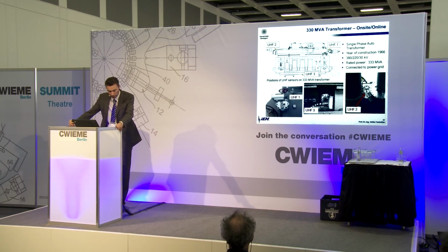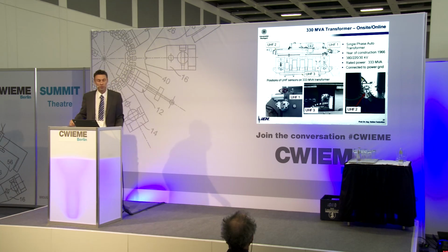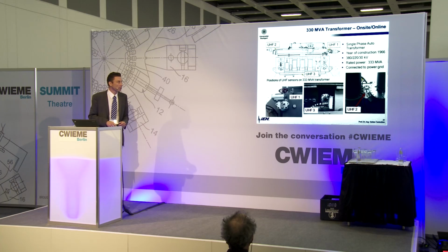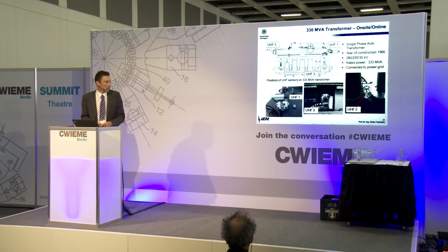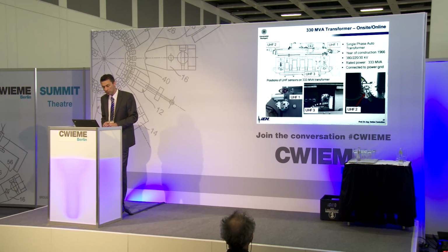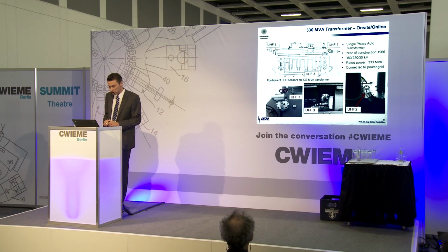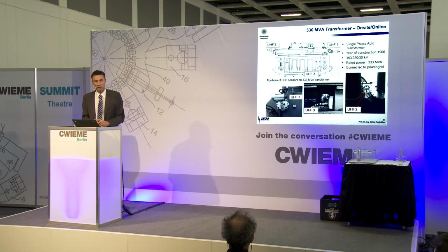I want to present you an example of this measurement. In this case, we have a single-phase auto-transformer, 380 kV. It was constructed in 1966, so quite an old transformer. And the oil analysis of this transformer revealed a high hydrogen content, and so partial discharges were expected.